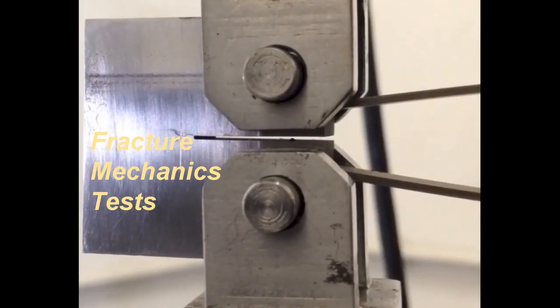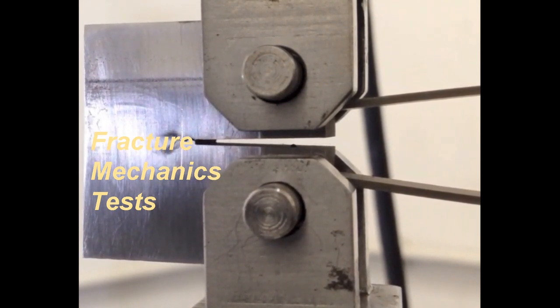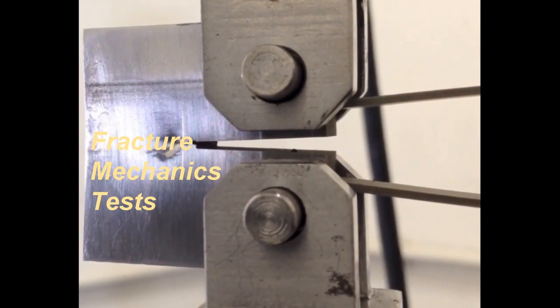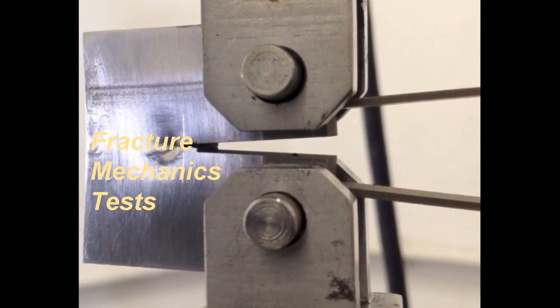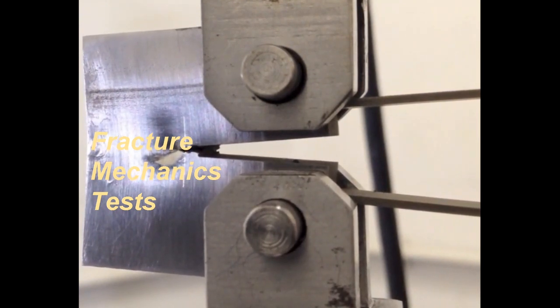Now that we know how to estimate K1 for each of the several notched plate cases we looked at, we also need to keep the applied stress intensity factor K1 below a limiting value that indicates the material's fracture toughness to avoid brittle fracture. We are going to use K1C for it. It has to be obtained from fracture mechanics tests.